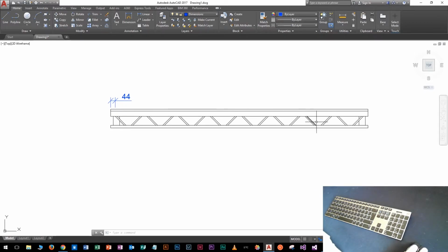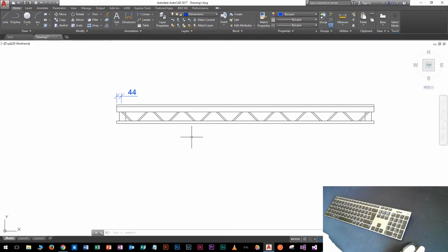And so the steel deck is now at 1 to 25, but the text and the dimension has remained at 2 millimeters. So it's like we've zoomed in. If we were to print this out, the text hasn't actually changed size. It's an illusion. It's the actual drawing that's changed size. It's got 25 times smaller, so it would fit on the page.